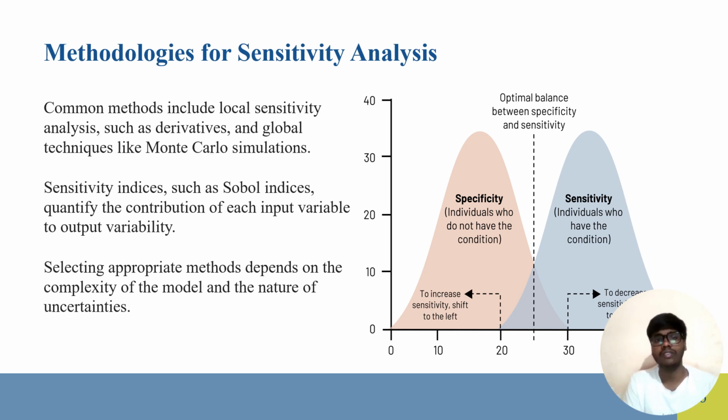And the methodologies for sensitivity analysis. Common methods include local sensitivity analysis, such as derivatives, and global techniques like Monte Carlo simulation. Sensitivity indices such as Sobol indices quantify the contribution of each input variable to output variability. Selecting appropriate methods depends on the complexity of the models and the nature of the uncertainties.